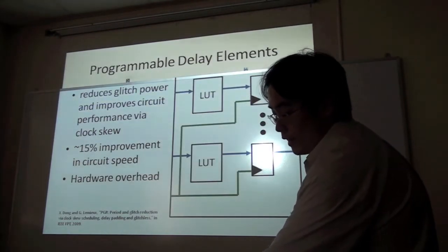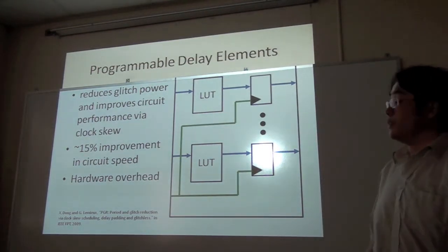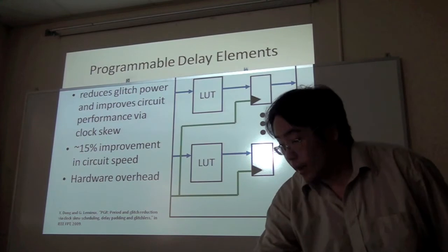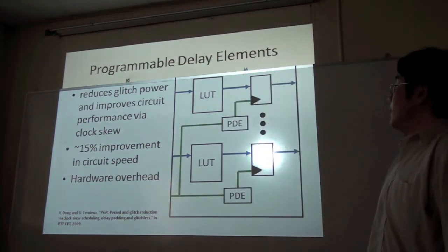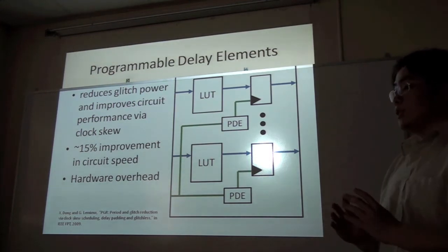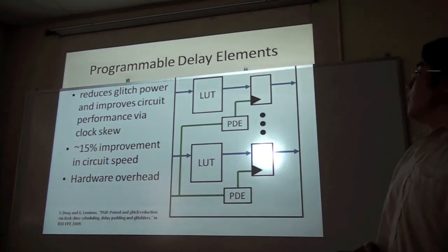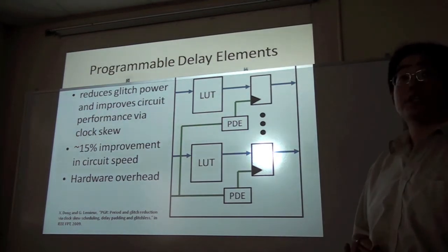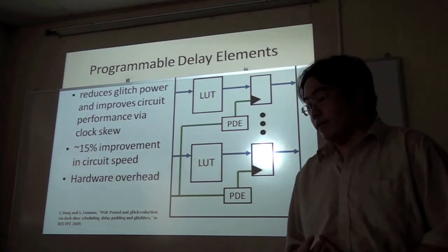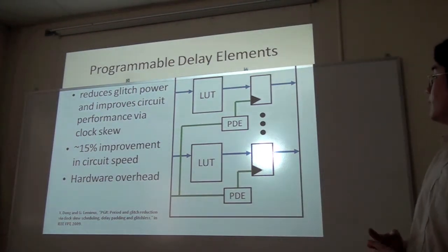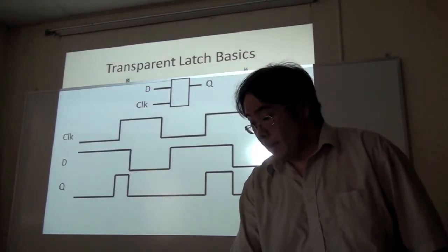Another approach, tried by Professor Guy Lemieux's group at UBC, is to attach a programmable delay element in front of every single flip-flop and adjust these PDEs accordingly so that we can reduce glitch power and improve the circuit speed using clock skew. He showed that this gave a 15% improvement in circuit speed, but this requires architectural modifications.